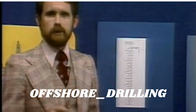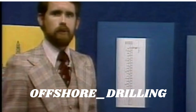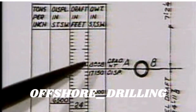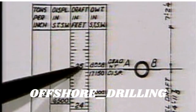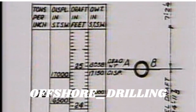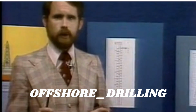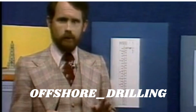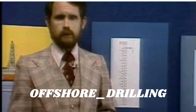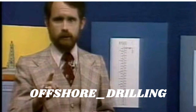At the top of this scale, on the line indicating the freeboard or maximum summer draft, we see the number 8538 in the deadweight column. Subtracting the deadweight for 23-foot draft, 7,050, from the maximum deadweight, 8,538, we get 1,488 tons, which is the amount of weight we can still load if it will fit.